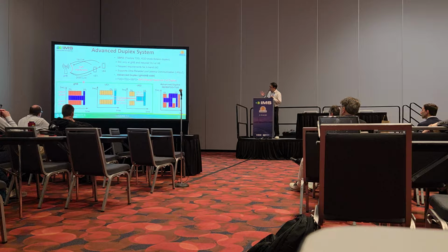So this is sub-band full duplex system. User equipment 1 and user equipment 2 are all doing time division duplex only, not full duplex. But user equipment 2, if they require uplink, they start to uplink at the given frequency band.